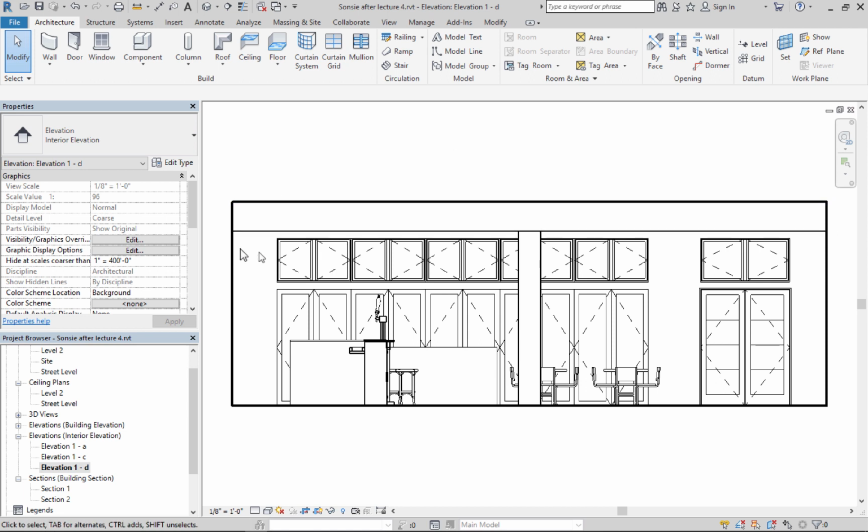Sweeps are elements which attach to walls and run along the length of a wall. You can put them in one at a time, or you can define them as part of the wall. I'll show you how to do both of those. First of all, you have to load in the sweeps.